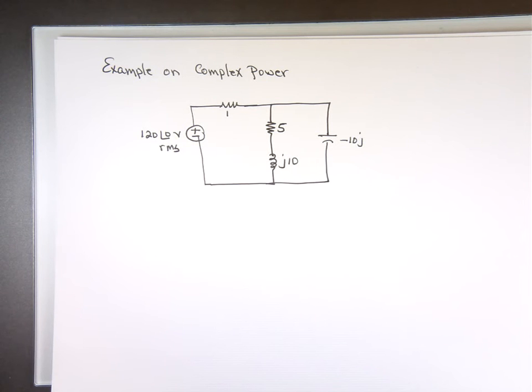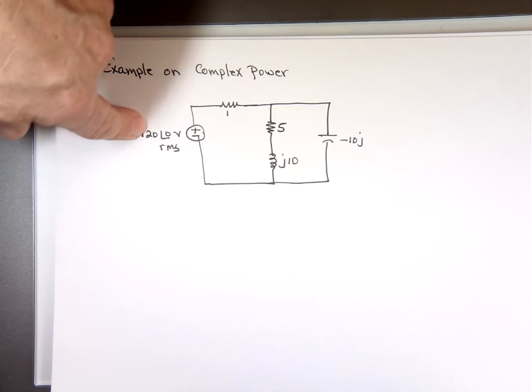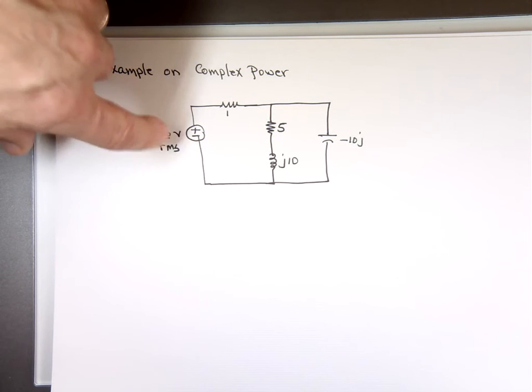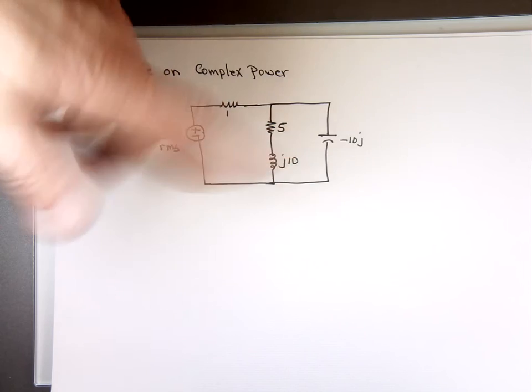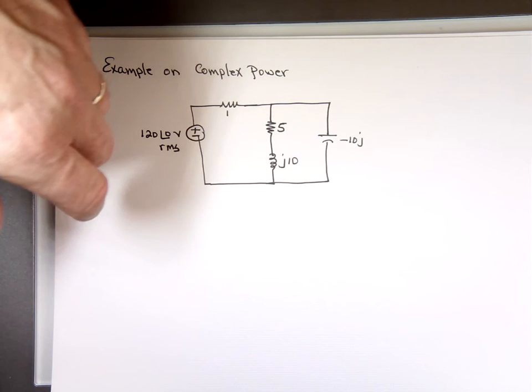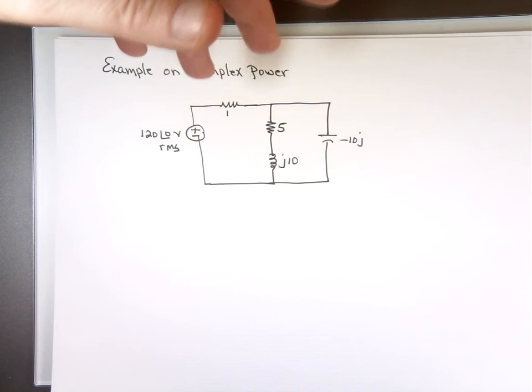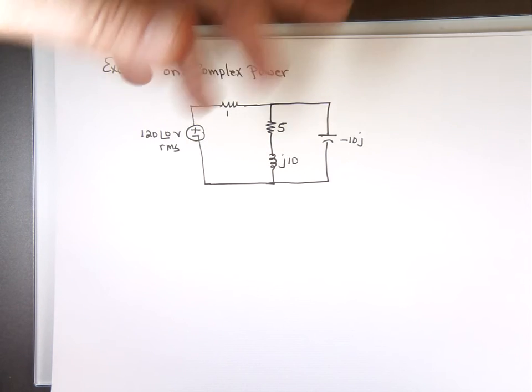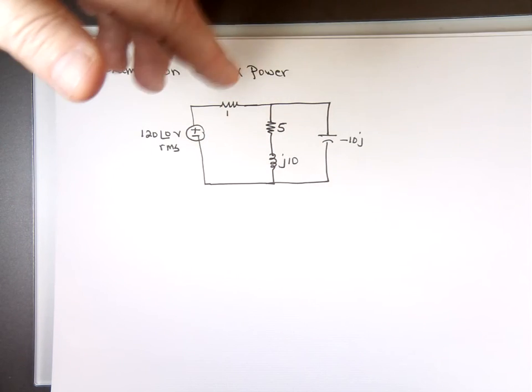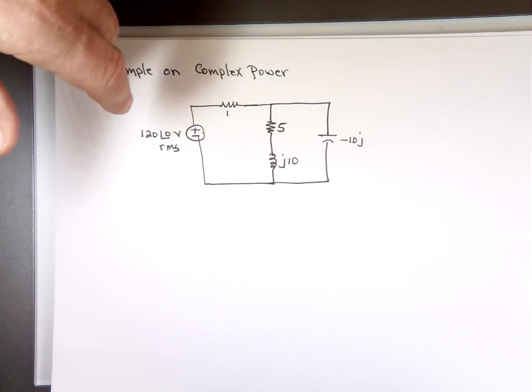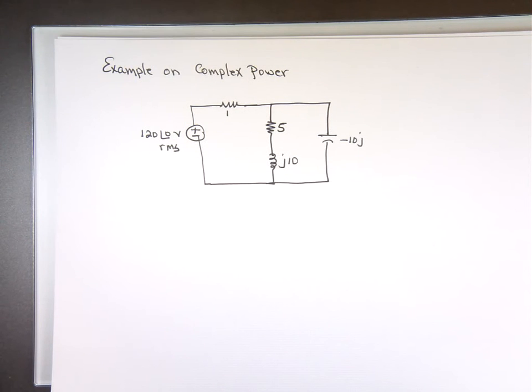If that wasn't VRMS, we would just divide by the square root of 2, right? Yes, if you want to switch that to RMS, you're right. You divide by the square root of 2, because of sine, cosine. But if you want to use complex power, instead of VRMS I conjugate, you can do 1/2 Vmax I max conjugate. Yeah, VI conjugate.